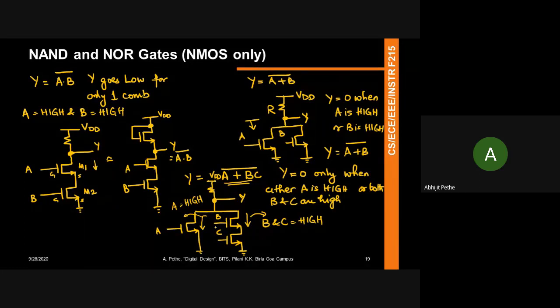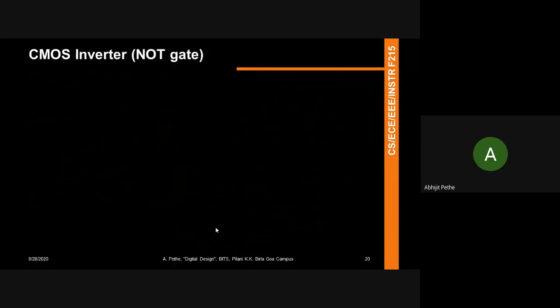Okay. If there are no other questions, now let's look at this. I gave you one question at the end of last class. I don't know how many of you got to thinking about it. That is CMOS technology. So why is CMOS technology used? CMOS technology is your low power technology. It has the lowest leakage among all the MOSFET technologies available, right? So hence CMOS is the most prevalent technology. Okay. So let's think about the circuit I gave you yesterday.